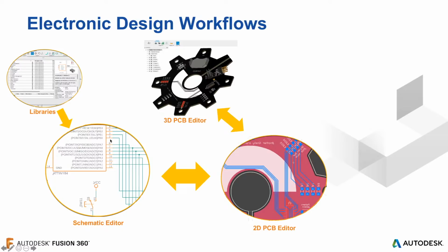Once you place enough components on your schematic, you'll be defining your connections, which is basically these green lines that you see here. You're going to be actually placing those connections. Now, you don't have to finish the schematic to start working on the circuit board, but you can actually now start working on the board. So from the schematic, I'm going to go over to the circuit board.